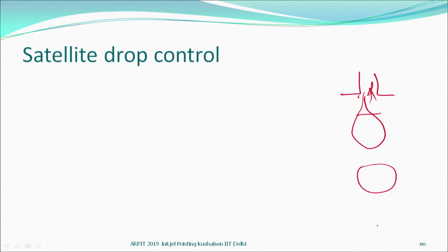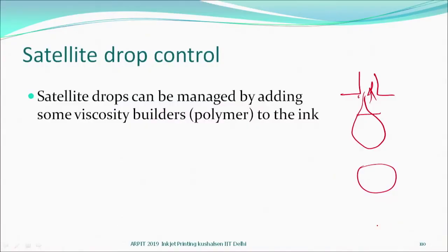Then what do we do? Can we control satellite drop formation? Yes, adding some viscosity builders. Remember, the ink is a low viscosity fluid. We are not interested in high viscosity, obviously not like the way the print pastes are, but increasing viscosity too much would mean more pressure has to be applied before a drop can come out.